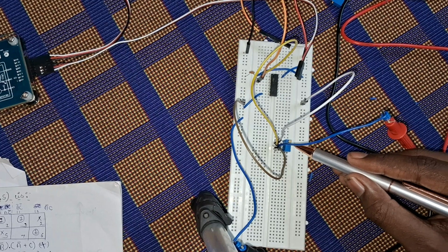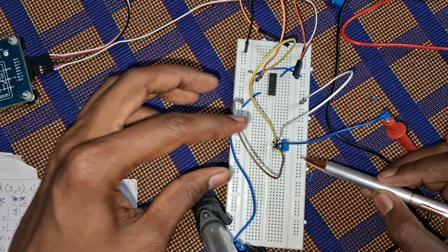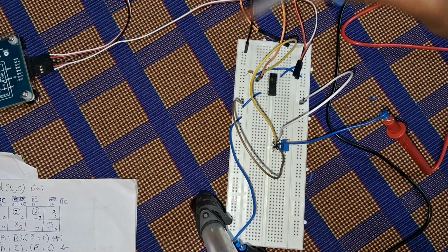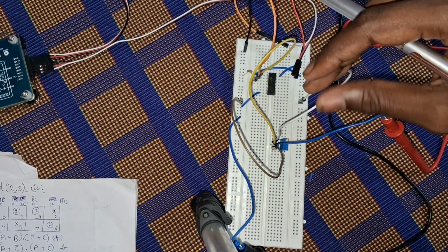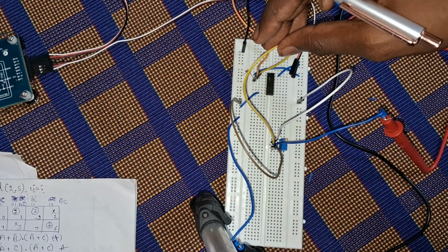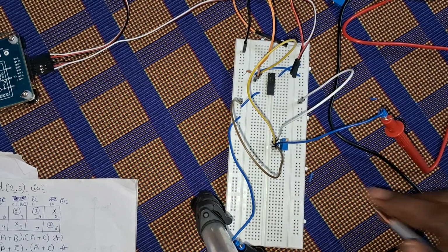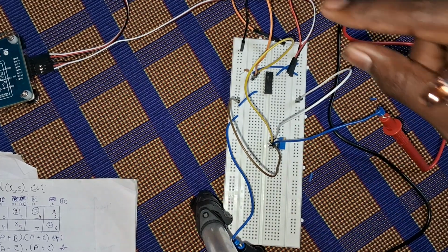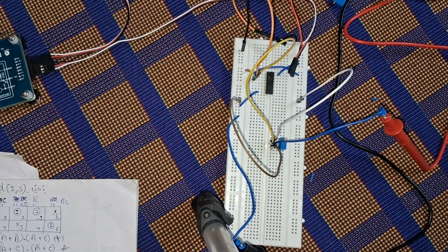Basically it acts like a voltage divider circuit. Here you can see at the last point, the third pin, we will give zero voltage, that is, ground voltage. You can see this one is the ground voltage. And the second pin, this white one, we will give plus 5 volts, and the middle one, the yellow pin, is a variable voltage pin. When we move this knob, the voltage varies because the resistance varies, so it changes the voltage.